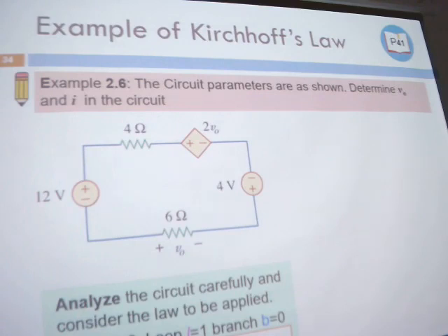Here we can see the independent node number n is equal to 0. Clear? And loop L equal to 1, because here we just have one mesh. In most cases we consider a mesh as the independent loop. Understand? So here our loop number L is equal to 1, and our branch number B is equal to 0. So for this we can say we just have one KVL equation. Understand? Clear?